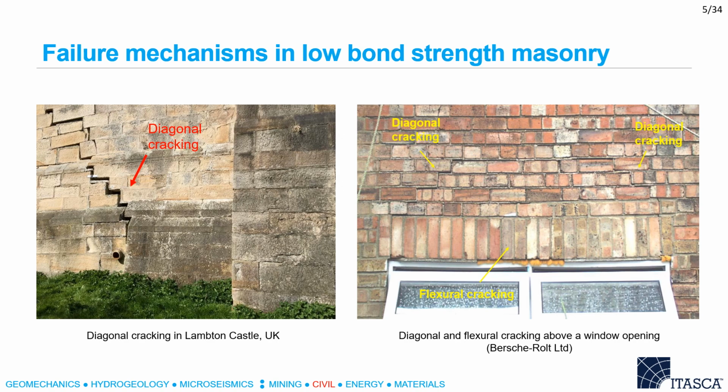Now, since old and deteriorated masonry structures are typically characterized by low bond strength, cracking is often a result of the debonding of the masonry units from the mortar joints. Given the importance of the masonry unit to mortar interface on the structural behavior of aged masonry structures, micromodeling approaches, i.e. those based on the discrete element method, are better adopted to simulate the serviceability and load carrying capacity of such structures.